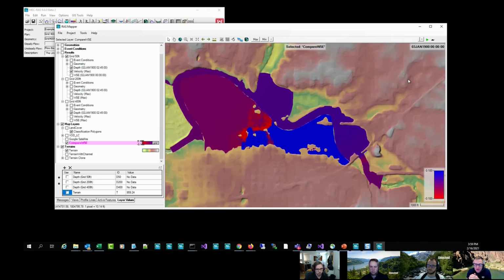In this case, when we're using the RASter Calculator, we don't have that capability to brute force, and we're just looking at time steps. So max depth times max velocity is not always going to give you the answer that you're hoping for. But that's a little bit more complicated problem than we have time for today.